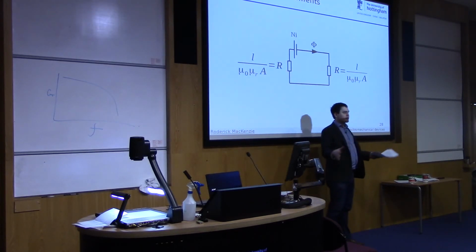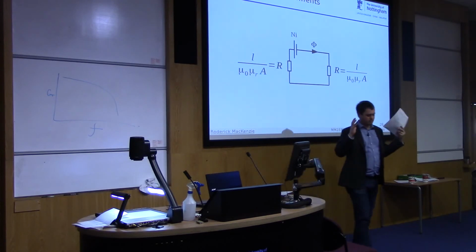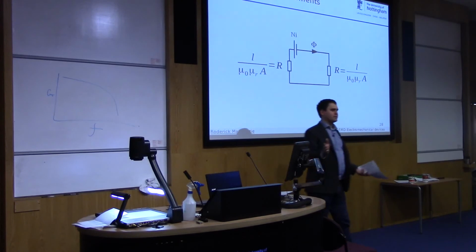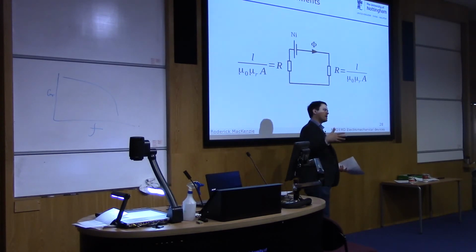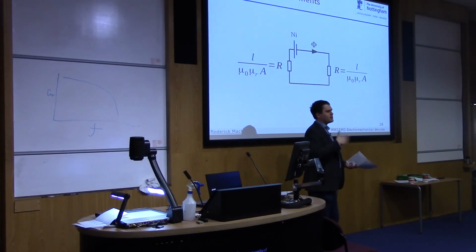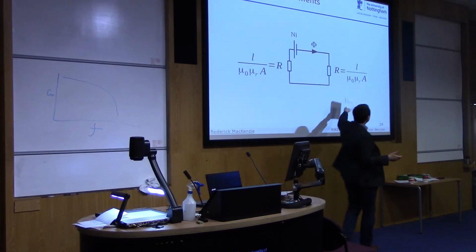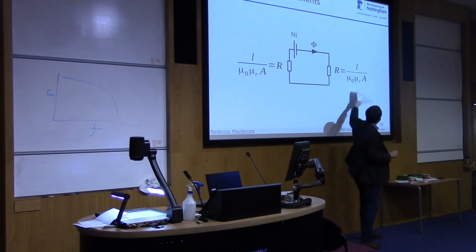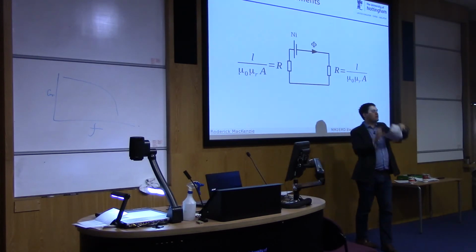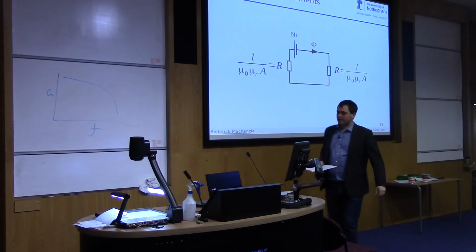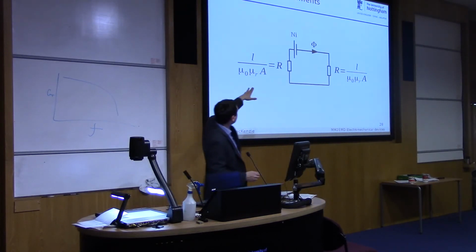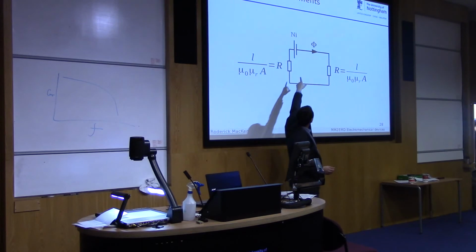At this stage you're just doing this with a DC magnetic field, so the magnetic field is basically stationary. When you look at materials in frequency domains, when you have magnetic fields changing at megahertz or kilohertz, this value of mu r changes a lot as a function of frequency. We don't need to worry about that. And A is the cross section of your material or your magnetic circuit. So we've got our resistances, and we've got our flux that's being generated.